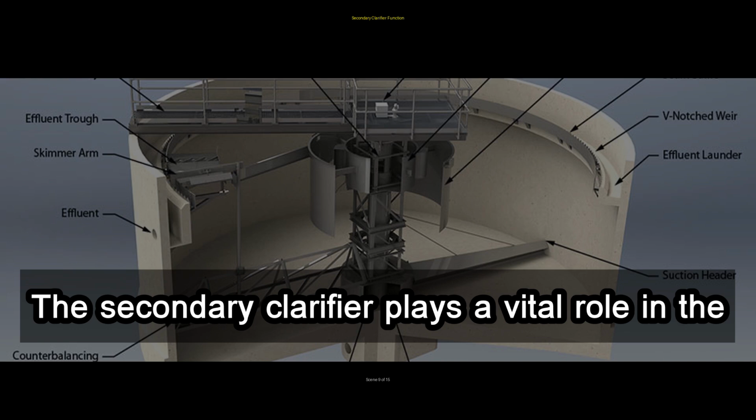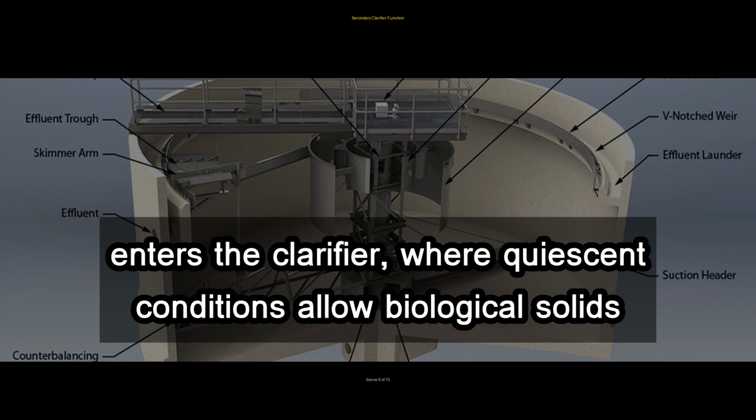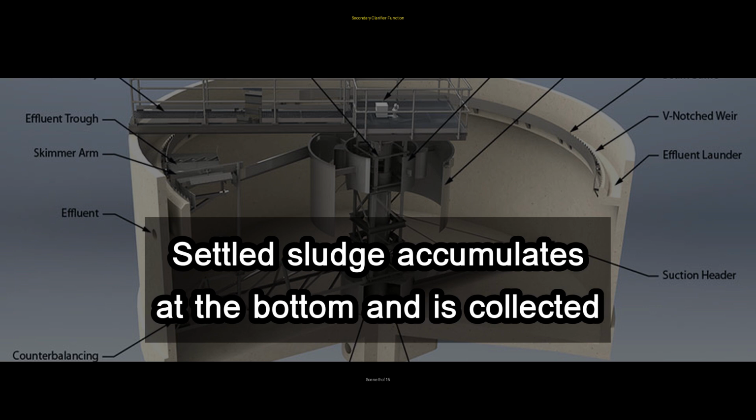The secondary clarifier plays a vital role in the activated sludge process. Mixed liquor from the aeration tank enters the clarifier, where quiescent conditions allow biological solids to settle. Clear treated water rises to the surface and flows over weirs for discharge or further treatment. Settled sludge accumulates at the bottom and is collected by rotating scrapers.